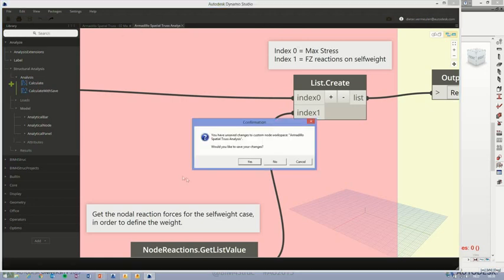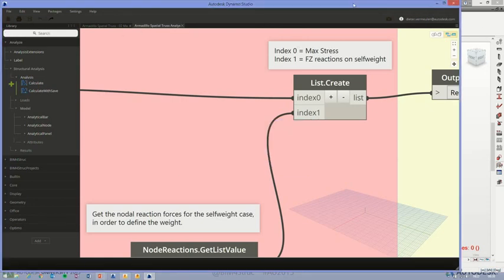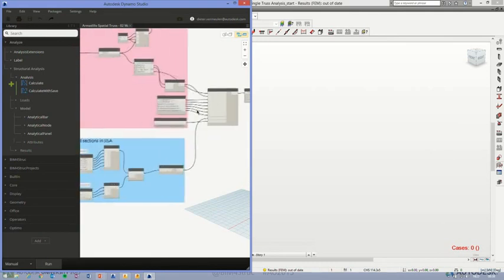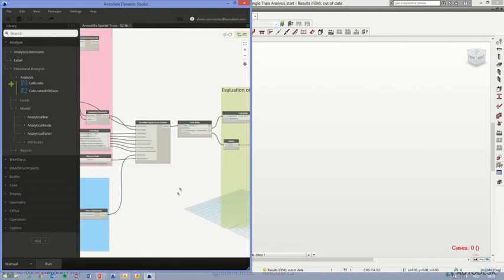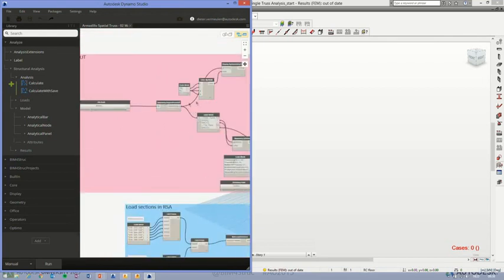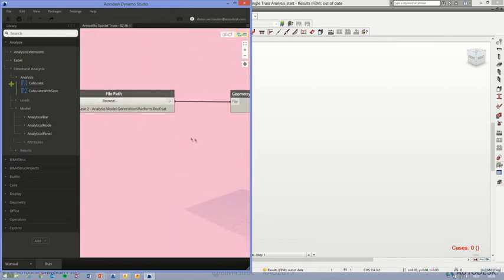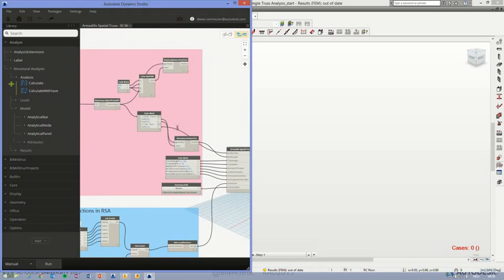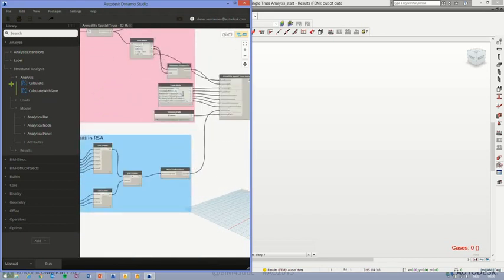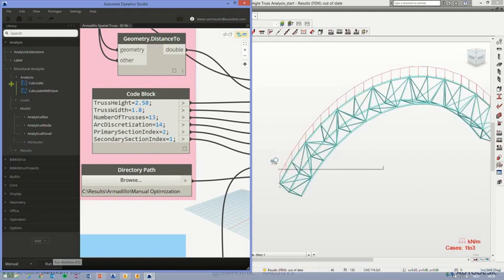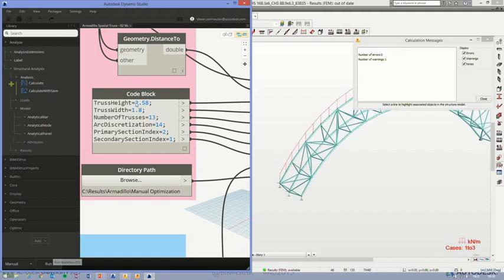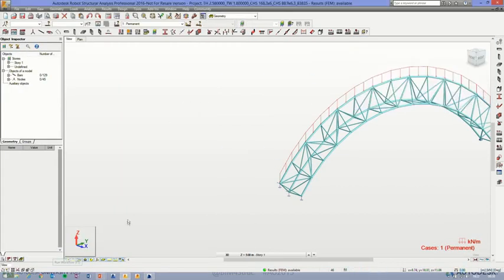How will I decide which truss to take? Well, you will take the longest truss. That will be the most negative case. So try to find in Dynamo the curve with the longest length, and then take that index and take that truss and work on that. Which means if I would reposition all the trusses by, for instance, saying I want to have 25 trusses instead of 18, then another element will be identified as the longest truss. Okay? So that will happen in that part of the analysis.